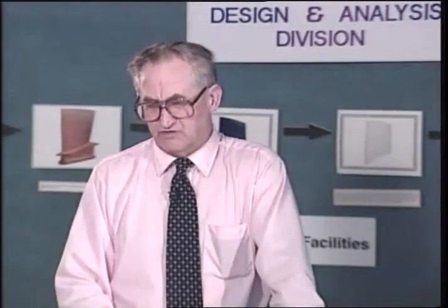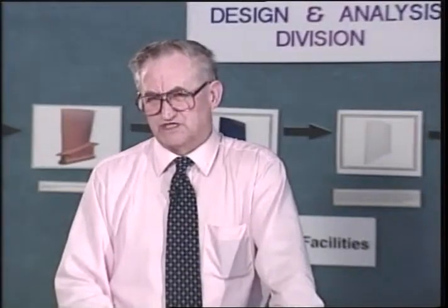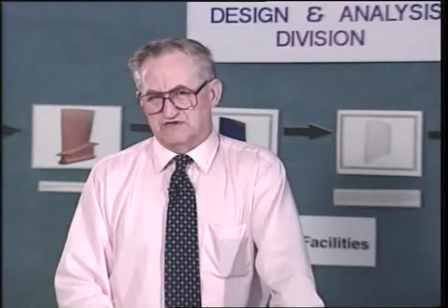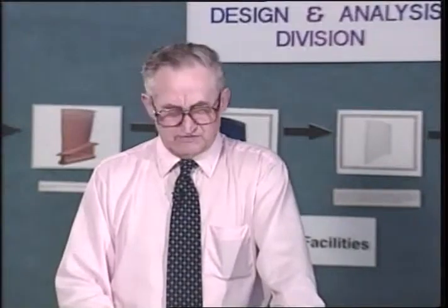Sometimes you have trouble passing this test with these pull stem rivets. So a lot of the manufacturers have had to go back and revise things to get a little more pull in the system so that they can lock the rivets. So that's what that one is used for. That one there would be for the blind fasteners.